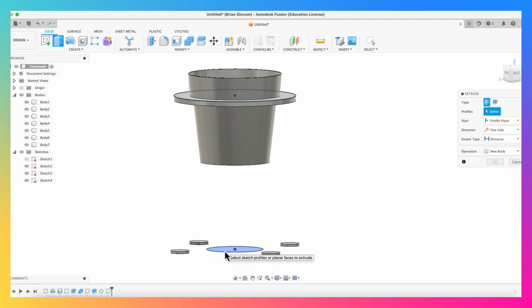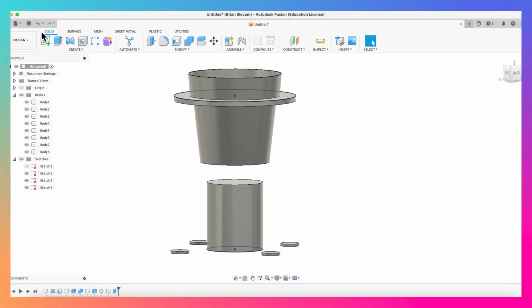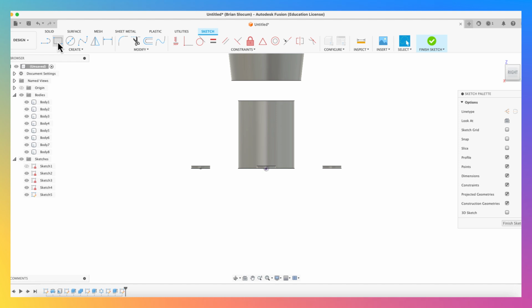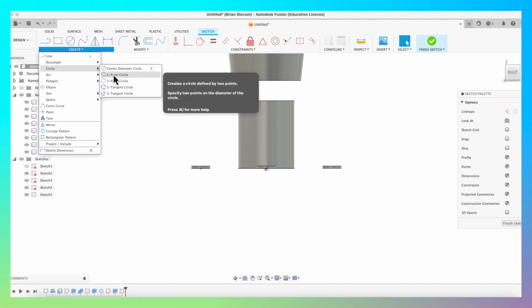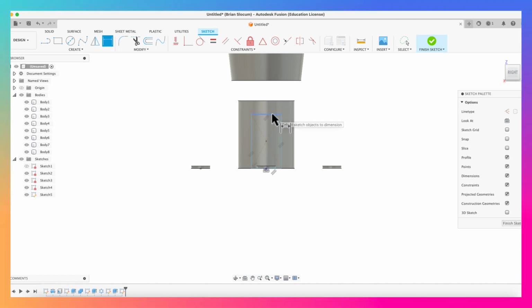I'm going to go ahead and extrude this guy up, and I don't know, we'll leave that all out of there. So we'll say we'll come up like 1.75. All right, I'm going to create a little bit more interest here, so I'm going to create a sketch, this time on that surface. And I'm going to use a center rectangle. And this, I know, seems sort of arbitrary, and it is, right? And that's the beauty of this thing, is that we are really making this arbitrary here. And we'll say this is 1.25. Okay.